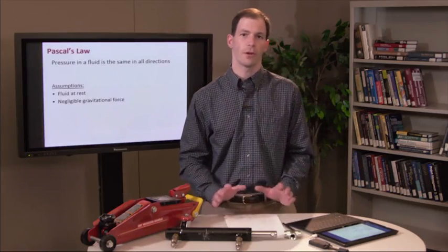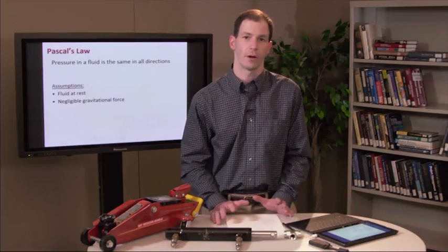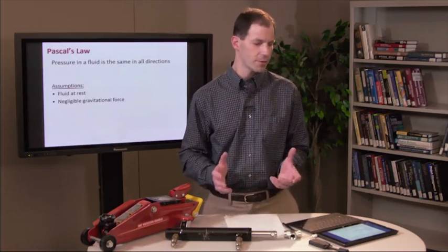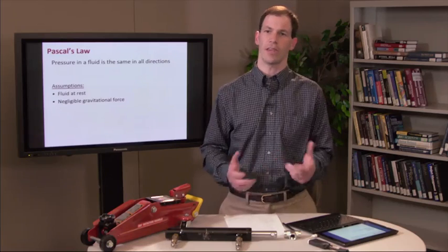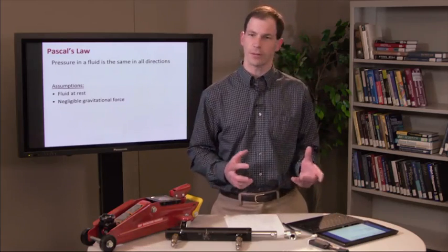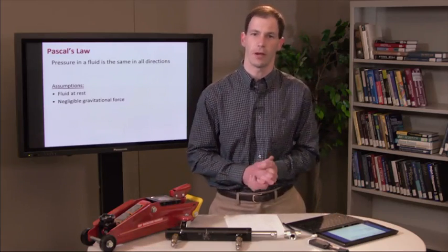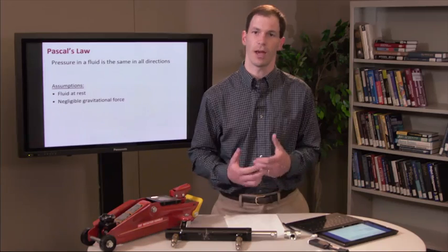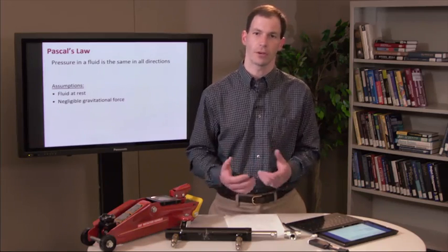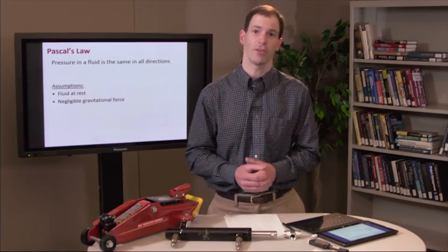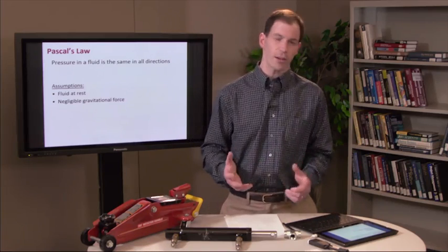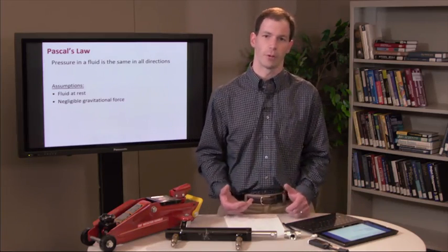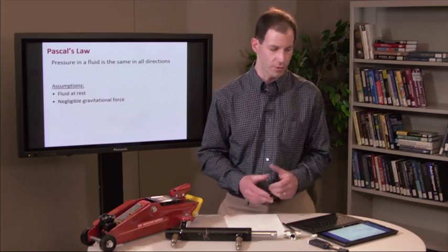So our first fundamental law that we're going to look at is Pascal's law. And Pascal's law simply tells us that the pressure in the fluid is the same in all directions. Now, there's two major assumptions that you have to pay attention to here. First is that we're assuming the fluid is at rest. So it has no velocity, has no viscous components to it, has no kinetic energy that we're paying attention to. The second is that the gravitational force is negligible, and we'll talk about this limitation in just a moment.